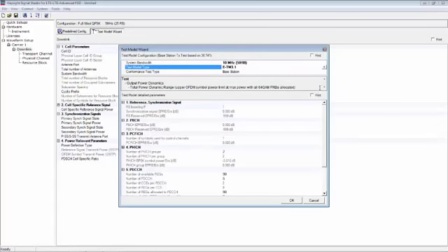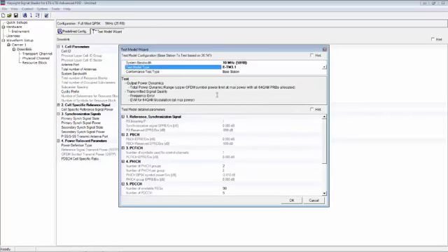And as you can see here in this section of the graphical user interface, the different types of tests that this particular test model type is applicable to, you will find that EVM is one of the properties that can be characterized by this test model. The ETM 3.1 configuration is one of the 4 possible test models used for EVM conformance testing, and is the only ETM with all PRBs set to 64 QAM, which is the highest order modulation supported.